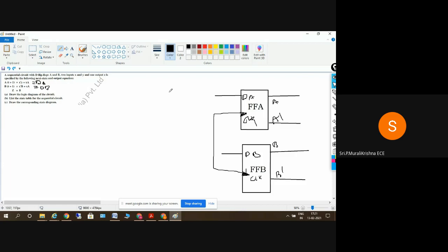So we'll be having an OR gate in front of the output, for the addition of x bar y and xa. One term is x bar y, and the other one is xa. So we will be having two AND gates here. Okay, and the AND gate outputs are like this.